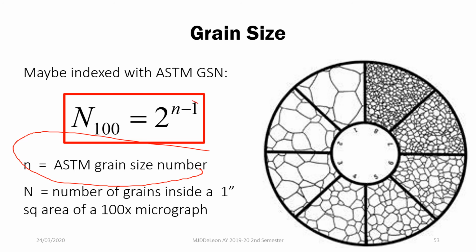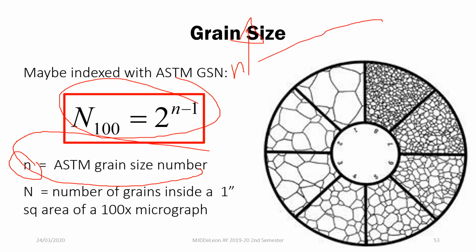And using this formula, we can get yung small n natin or yung grain size number mo. For now, what you need to learn is just pag mas mataas yung grain number natin, if n is high, ibig sabihin, mas polycrystalline yung material. Mas maliit yung grains nila. If n is lower, let's say 1, the material would have larger grains. It would be less polycrystalline.